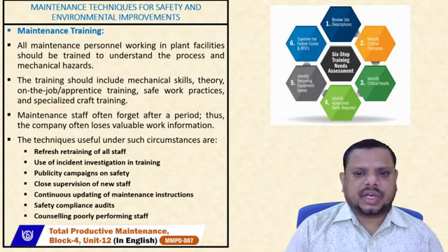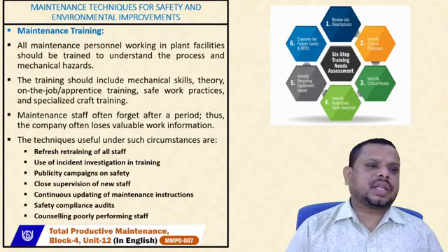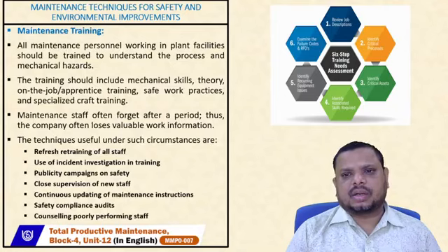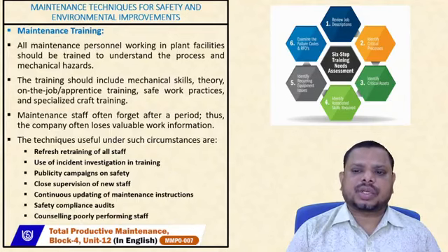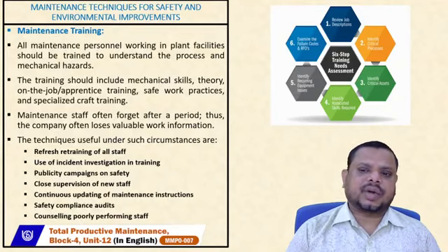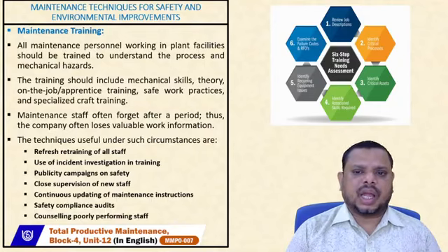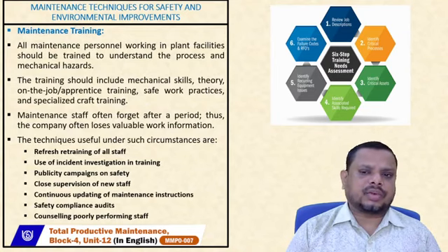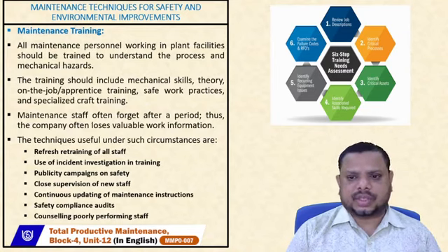Apart from these, there are other steps that improve maintenance skills among workers. The first is that you must review job descriptions. Second, identify the critical process. Third, identify the critical asset. Fourth, identify the associated skills required. Fifth, identify recurring equipment issues. And sixth, examine the failure codes and RFO reports for the operation activities.